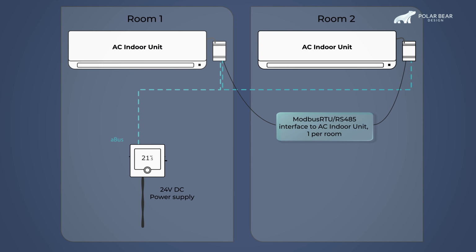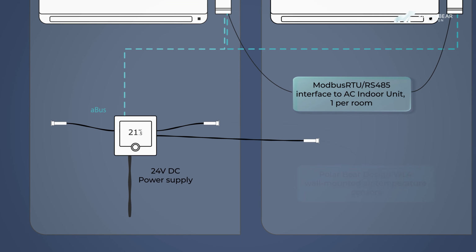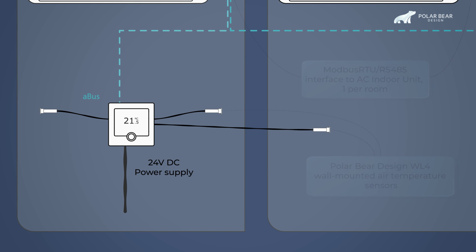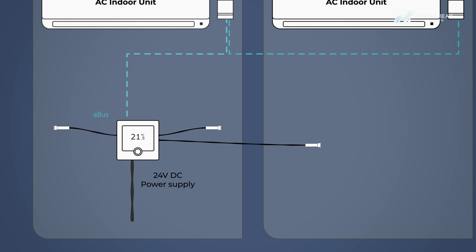Each Zentium 2 or Inertium has a built-in air temperature sensor, plus 5 ports to wire in additional sensors. These extra sensors can be used to measure air temperature or floor temperature in either of the 2 rooms. It's possible to assign multiple sensors to the same task, say air temperature measurement in room 1. And when you do that, those measurements are blended using a sophisticated averaging algorithm.